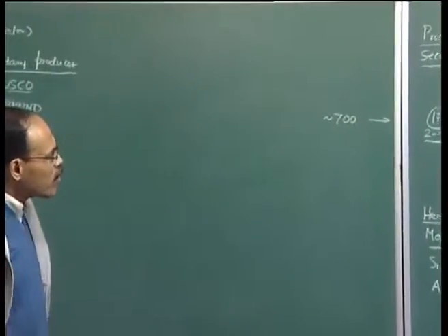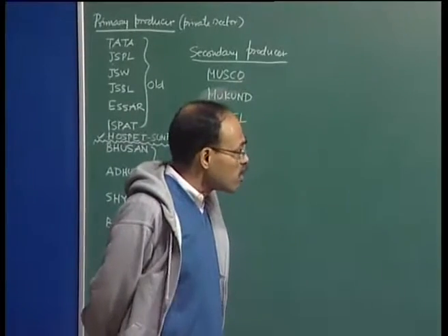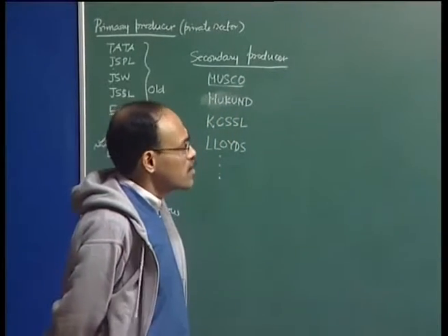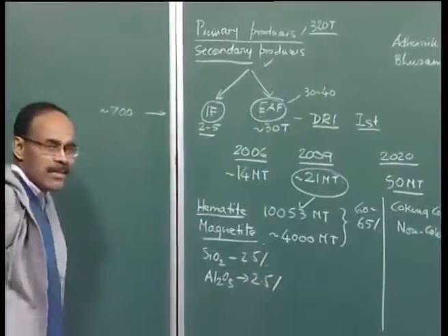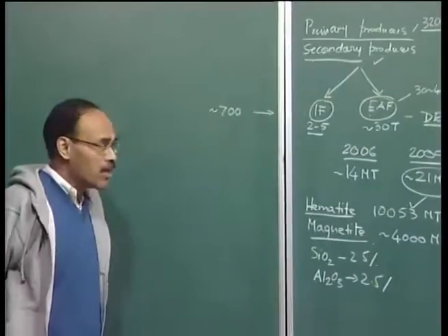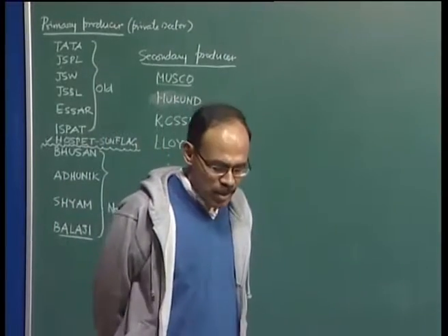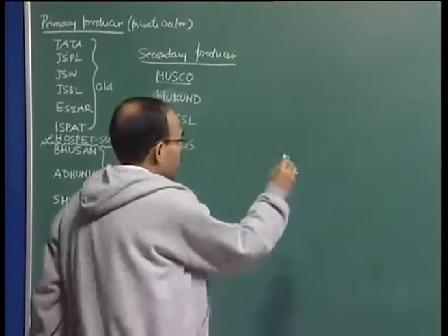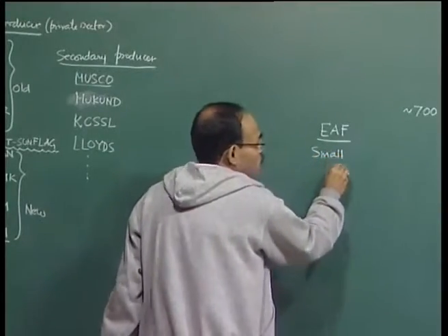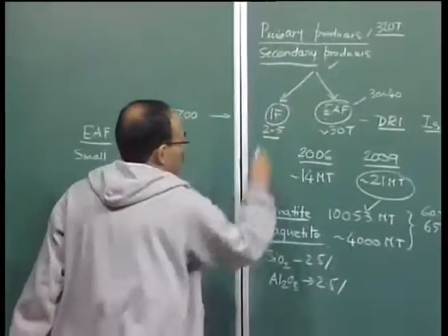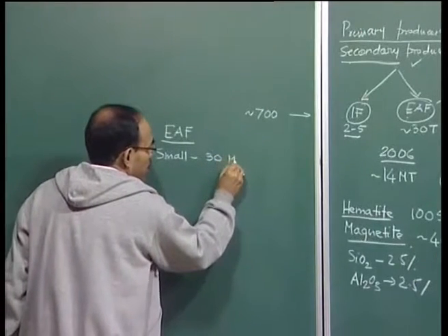So in the secondary sector that produces steel in this country, very interestingly, a major chunk of it comes from the induction furnaces, where the number is really enormous. It is basically because setting up an induction facility is extremely inexpensive in comparison to an EAF facility. Now, the electric arc furnaces in our country are also age old. Their sizes are small. What are the characteristics of EAFs in India, for example? It's a very small size. In advanced countries, you can see electric arc furnaces of about 400-ton size. In our country, the electric arc furnace size is small, barely about 30 metric tons.